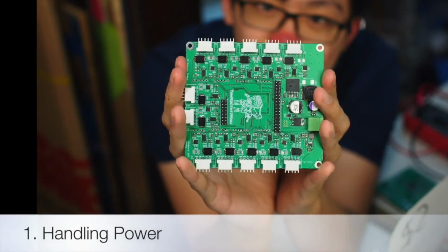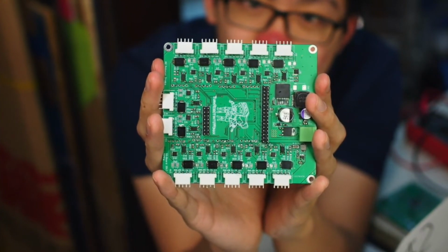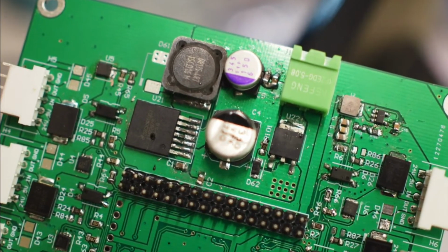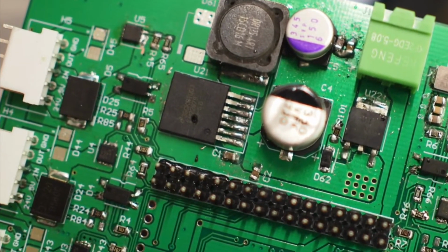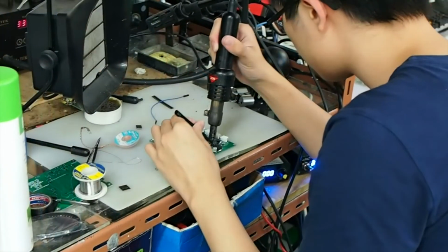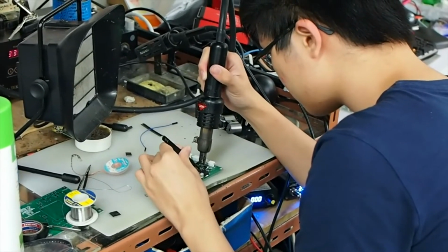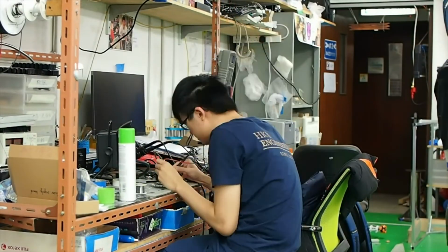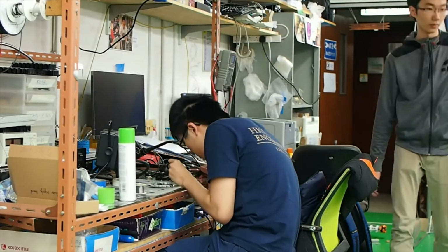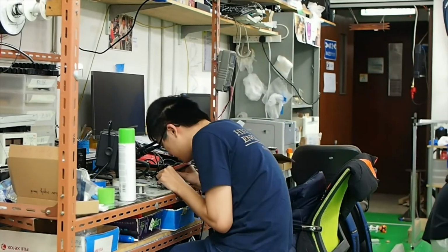Another problem that we encountered is in the designing of the PCB. Although we have done many calculations to make sure the components work as intended, sometimes wrong usage of the board will damage some components of the board. For example, the LM22679 integrated switch buck converter that provides the 5 volts got damaged when one of our teammates shorted 24 volts and 5 volts. We had to spend time repairing the board.